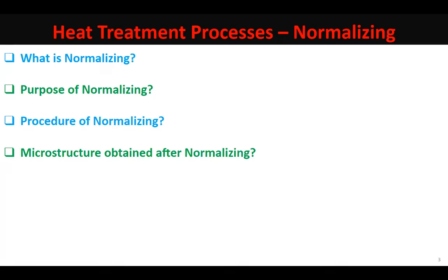So during full annealing, you can see from the iron cementite diagram that for any steel composition, what amount of pro-eutectoid ferrite or pro-eutectoid cementite is getting formed. Since in normalizing, cooling is faster as compared to equilibrium cooling, that is the cooling followed during full annealing, the amount of pro-eutectoid ferrite or pro-eutectoid cementite, as is the case, formed is lesser during normalizing.